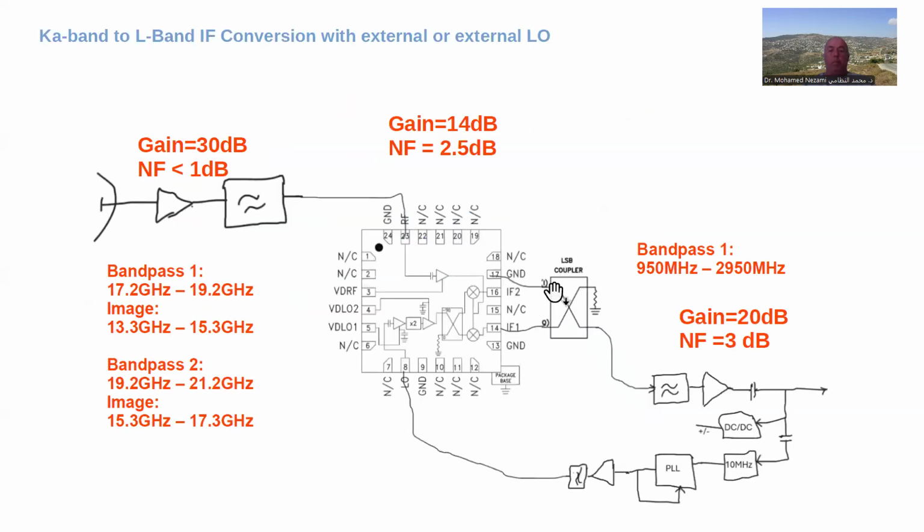If you go back to the mixer, here, the manufacturer used one, and the model that I get actually encompasses it. So all the models that I'm constructing are assuming that the hybrid I'm going to pick has the same performance, which it is not for sure. Now, these people here must have used a 50 ohm connectorized, probably 90-degree hybrid that is very expensive because it's broadband and really well matched in quadrature.